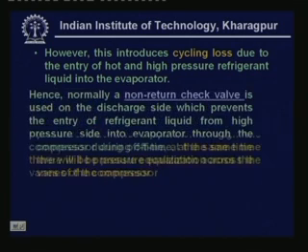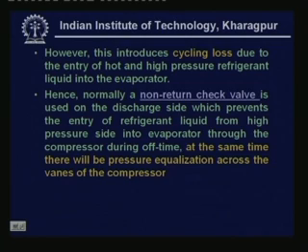Hence, normally a non-return check valve is used on the discharge side, which prevents the entry of refrigerant liquid from the high pressure side into the evaporator through the compressor during off time. At the same time, there will be pressure equalization across the vanes of the compressor.